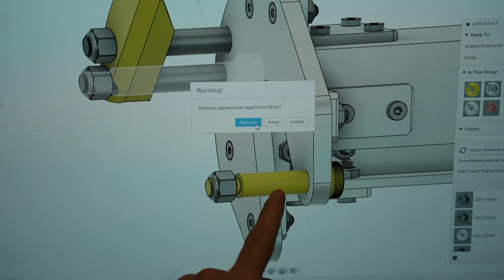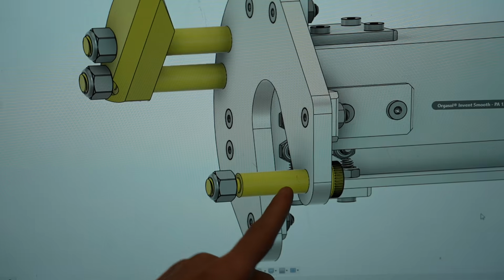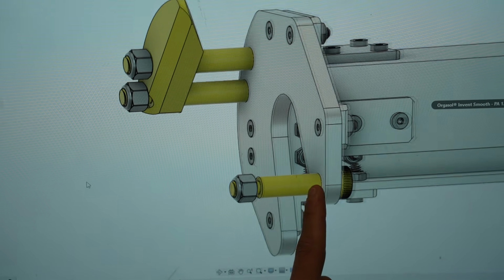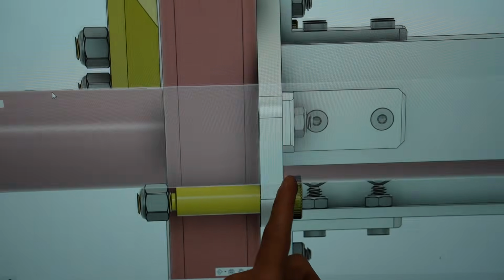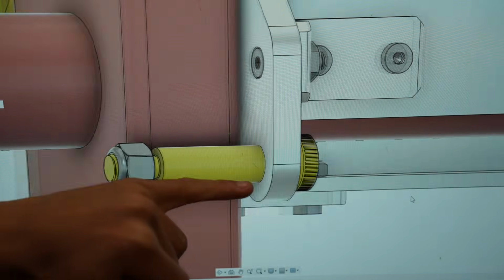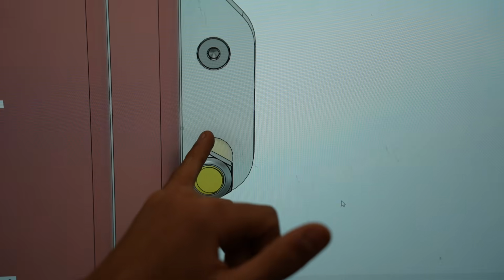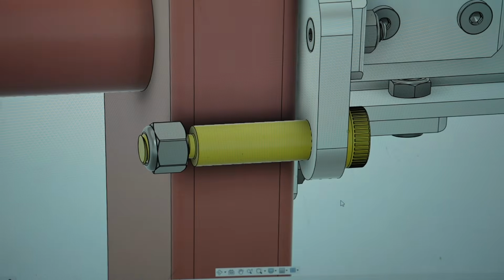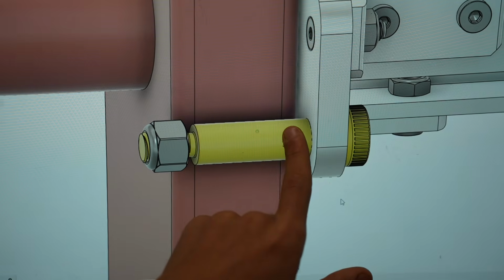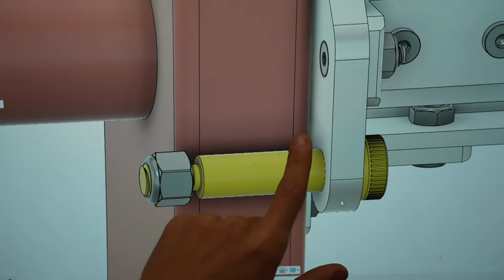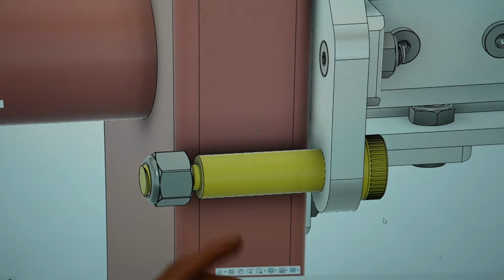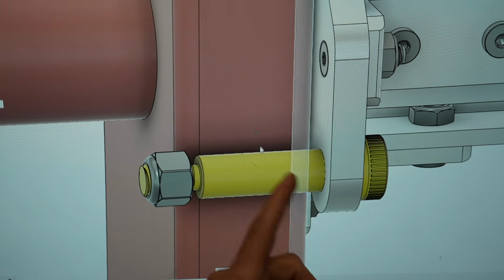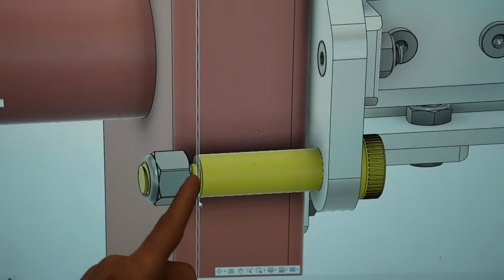So we're just doing our analysis on these bolts. Additionally, we're making a non-conservative assumption, which is that our force is applied about 2/3 of the way up our bolt here. Because as we load, and we verified this with finite element deflection, the bolt deflects away from the pole and our load shifts towards the root. It actually shifts all the way toward the root, at the start of this fillet here. But we're making the assumption that it's going to be half an inch up. This bolt will bend if you load it with 1,500 pounds from the very end, but that's not what's happening.